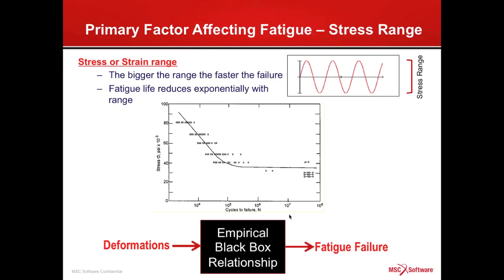So I mentioned there that we're considering the process of fatigue analysis as being an empirical proposition where we take stresses or strains and we use them to estimate fatigue failure. The traditional or one of the more normal ways of specifying this would be in some kind of diagram with stress or strain on the vertical axis and fatigue failure in cycles on the horizontal axis.